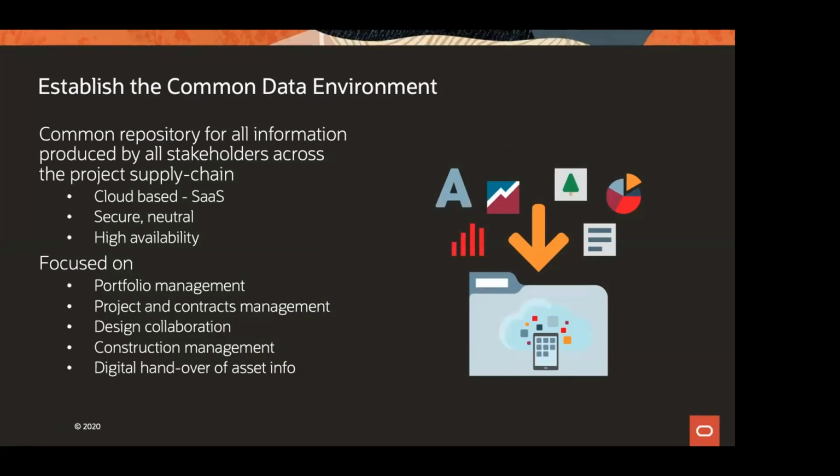And because a lot of projects are actually done on an international distributed team basis, you want to make sure that you've got secure, high availability for that system. A common data environment must not just focus on the 3D model. It needs to focus on the portfolio management information, cost and contract management, help the design collaboration process work, help the construction management process, and ultimately that digital handover of the asset information.